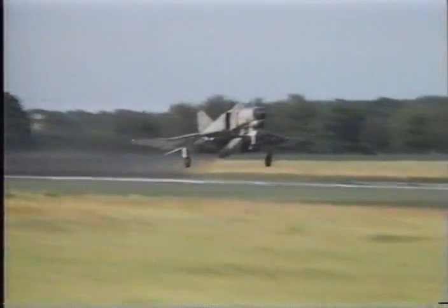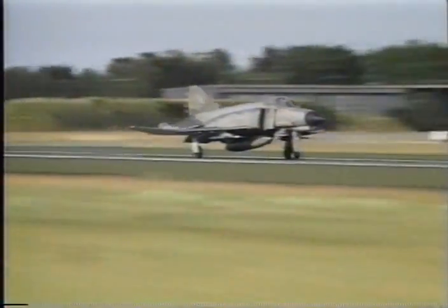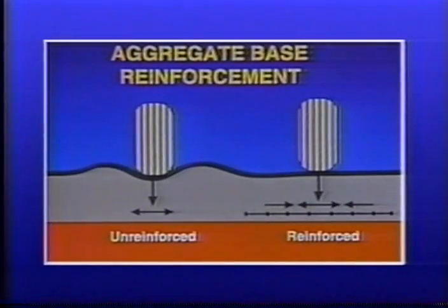Pavements have less tensile strength than compressive strength. Therefore, over time, heavy traffic loading causes them to deform and crack, even if the subgrade is not especially weak. Geogrids have been shown to have their greatest reinforcing effect when embedded in the lower half to 3/4 of the pavement thickness. This is because tensile stresses are higher at the bottom of the layer.